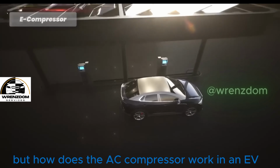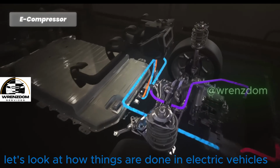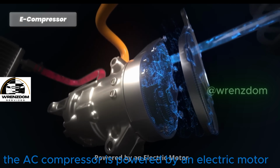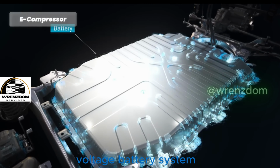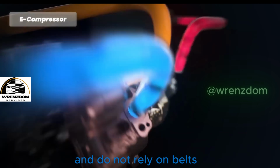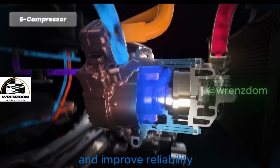But how does the AC compressor work in an EV? Let's look at how things are done in electric vehicles. In EVs, the AC compressor is powered by an electric motor. This motor is driven by the vehicle's high-voltage battery system. Electric compressors have fewer moving parts and do not rely on belts, which can reduce maintenance needs and improve reliability.